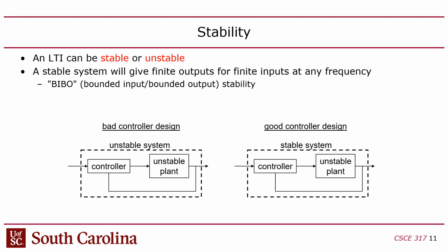Now you might say, well, come on, even code can't blow up into infinity. If you have a controller and it has an output signal, that signal is associated with a numerical value, which is stored in a register, and that register will saturate at some point. It'll go out of bounds. No computer can store a value that has infinite dynamic range, right? True, but it will eventually get to that point. It'll peak out and die, right?